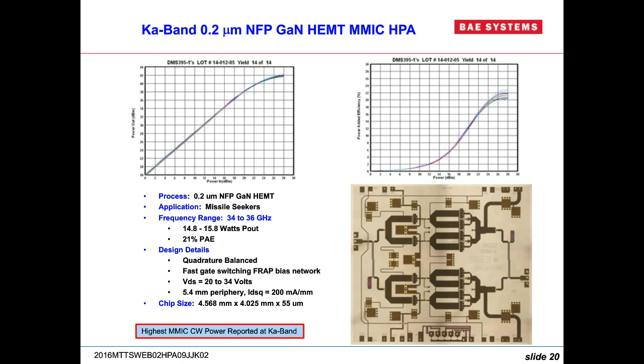Secondarily, GaN is a thermal limited device, and silicon is not as good in thermal conductivity as silicon carbide. People have tried other things like gallium nitride substrates, but they never really got commercialized. So basically that's your two choices today, silicon carbide and silicon.